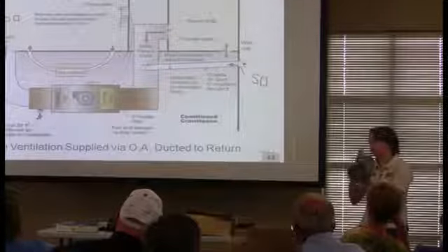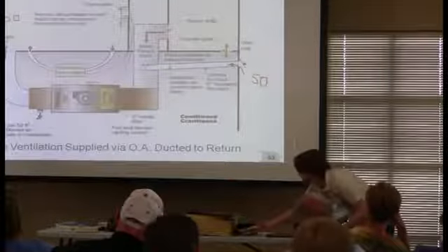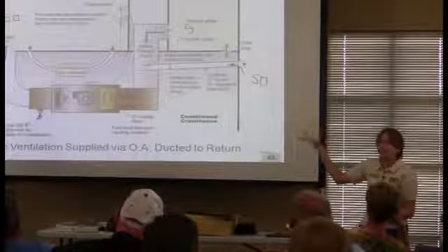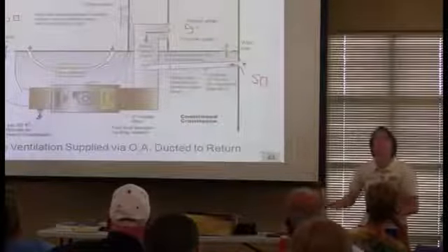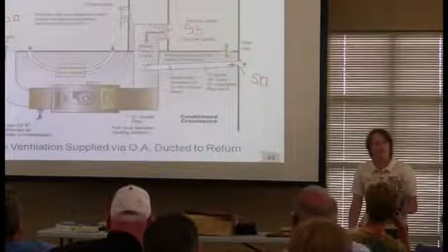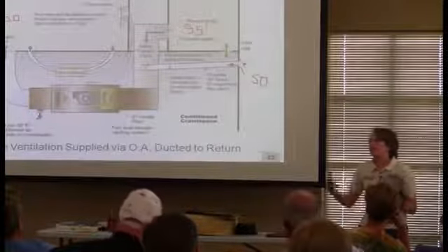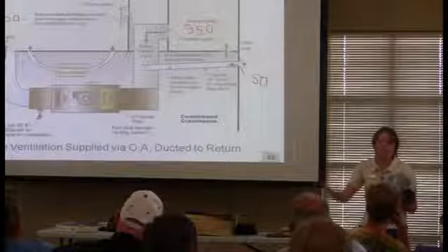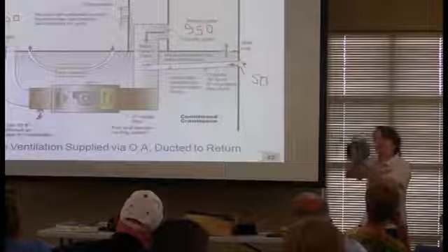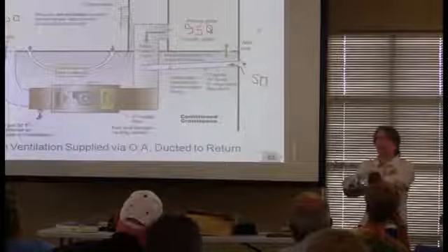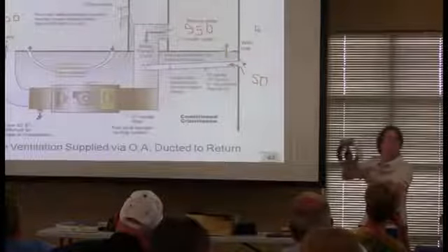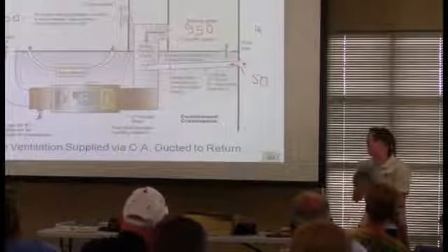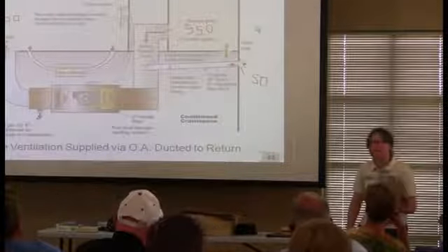And so what it does is there's a ventilation controller that says, I want to bring in 50 CFM for 15 minutes every hour. Now, if you are in a heating or cooling season and your equipment is already running, say for 20 minutes, it just opens up the damper. It has a mechanical damper, you can see the little switch on top, and it opens up and allows air to pass through. After those 15 minutes, it shuts and it's just operating normal.